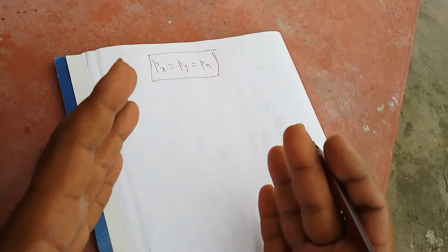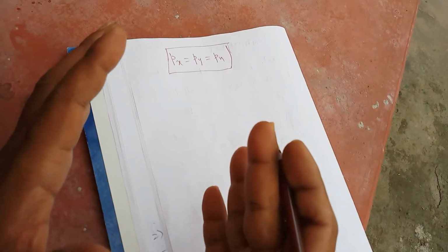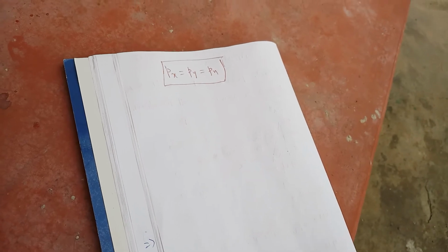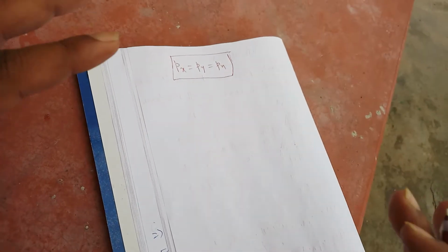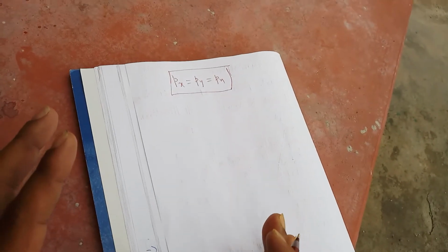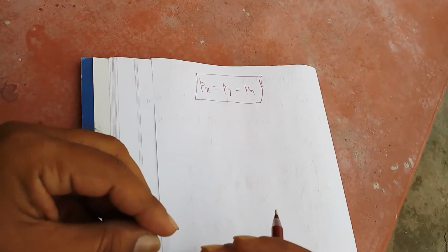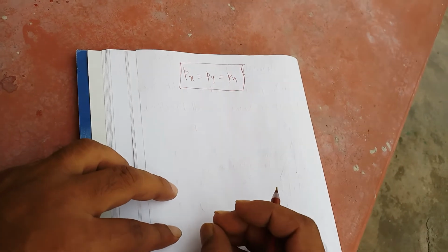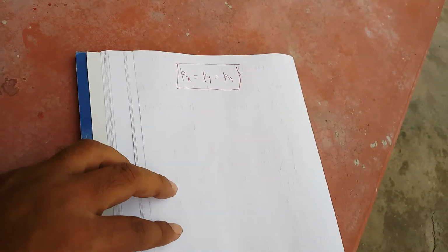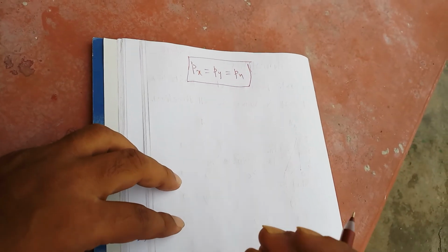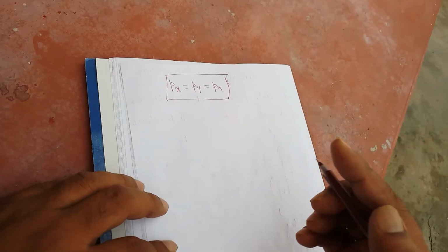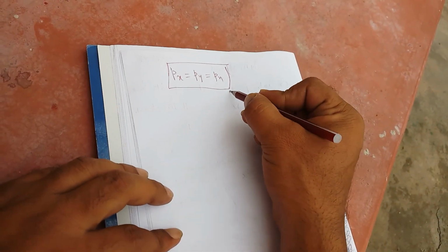You know that when the lengths delta x and delta y approach 0, that means the triangle or that fluid element shrinks to a point O. So we can say that at the point O, pressures from all directions are the same, and that is Pascal's law. So this is the theoretical proof of Pascal's law. Okay, fine.